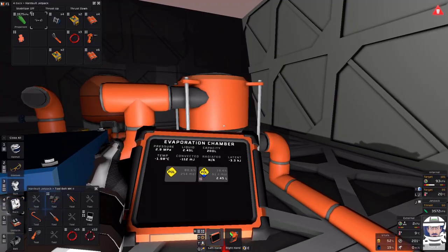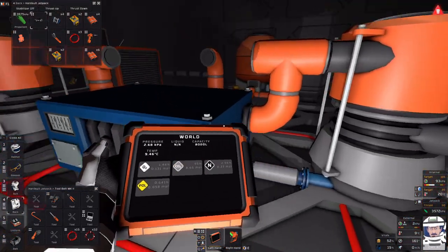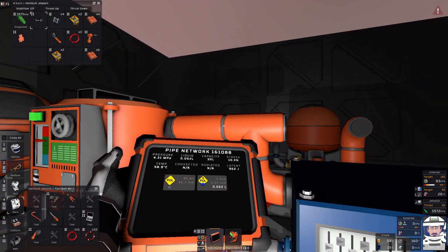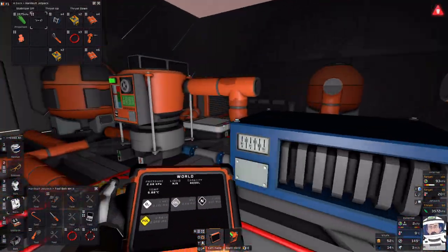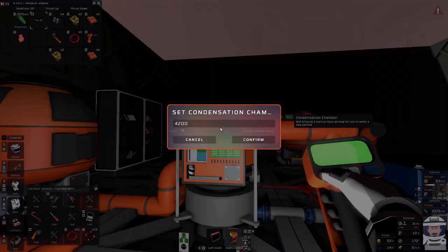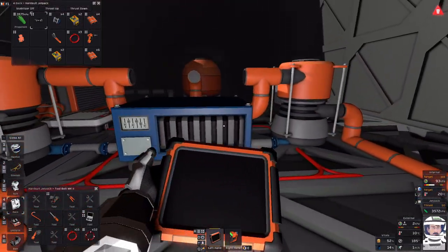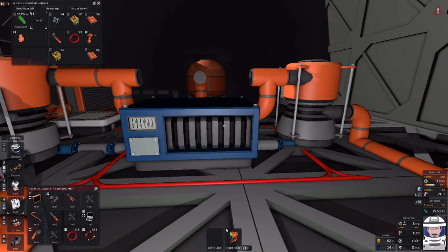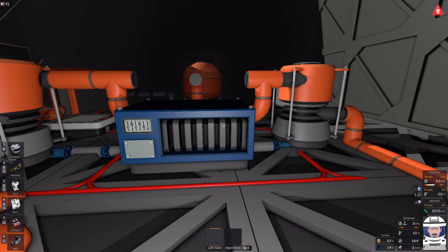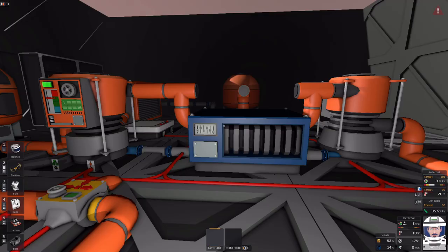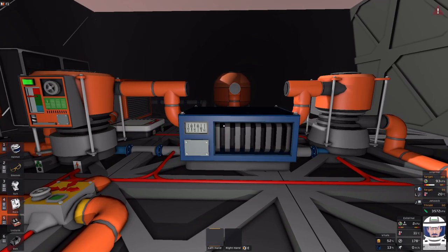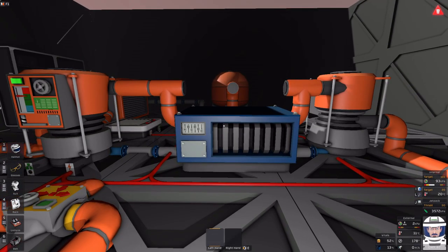Now it's still pushing some liquids out because I'm having condensation in my pipe network. Theoretically, you wouldn't have filled this to the point that this would happen, but this is what the safety margin is for. If you don't really need the systems to be throttled, you can go ahead and run them both at full tilt. Alright, and with that, that is how to build a simple phase change device loop for heating or cooling. Best of luck to everyone out there, and have a good time building.